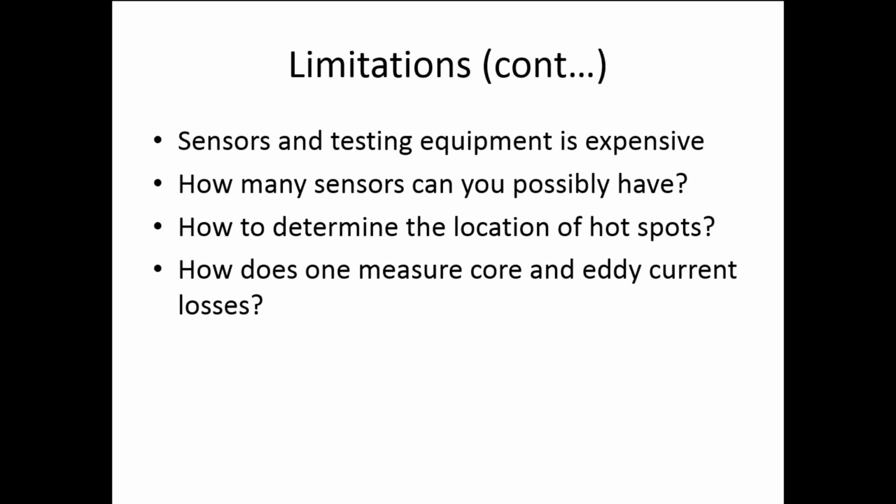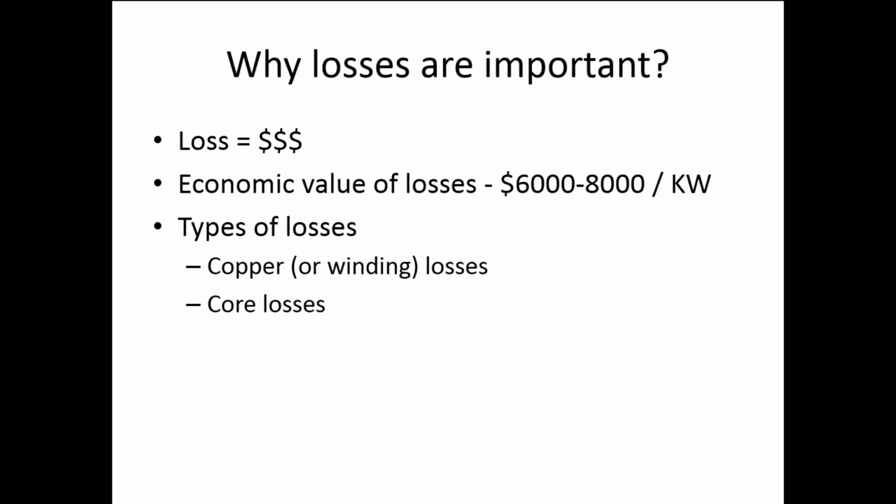So the location of the sensors, where to locate them, is always going to be a big challenge. And finally, you can measure things like flux, you can measure temperature, but how can one accurately measure the losses, basically the eddy current losses and core losses and so on? There are some challenges involved here. These are some of the limitations that the industry faces today.